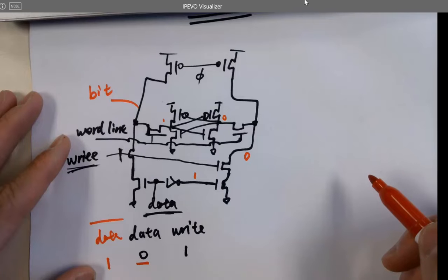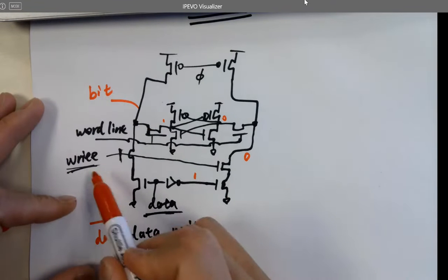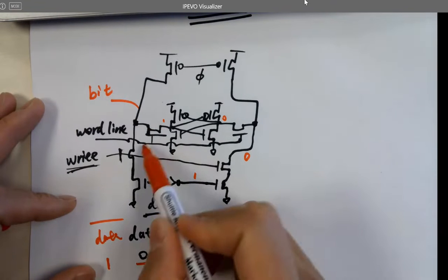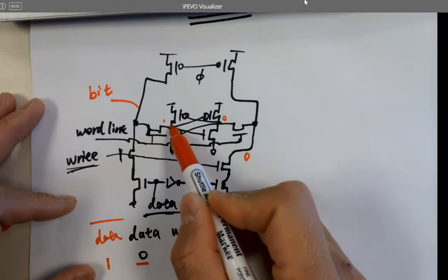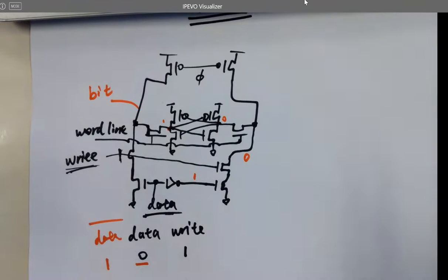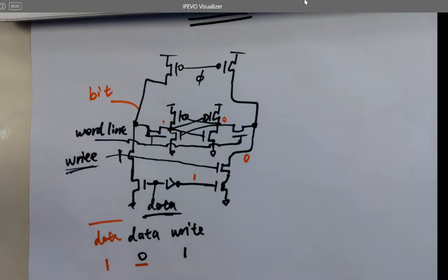It's a complicated circuit. Oh wait, so the reading part. Word line. The word line just turns these two on, right? So the data can be passed to the storing latch. For reading and writing, you turn it on. It just has to be on when you are doing something to the latch. It's like another signal container outside of the latch.